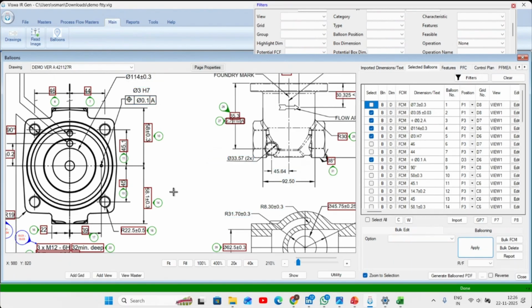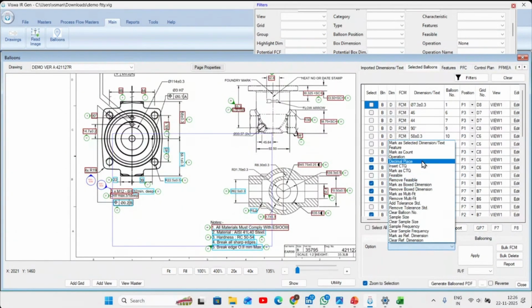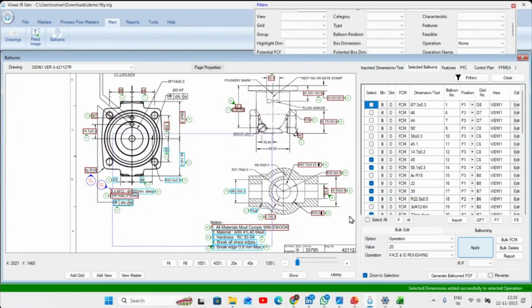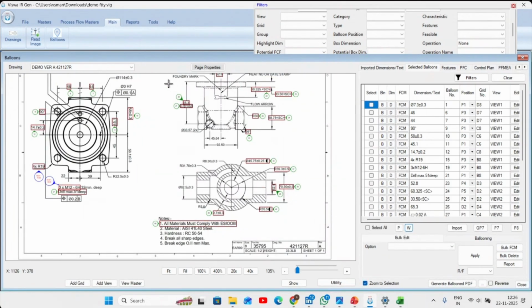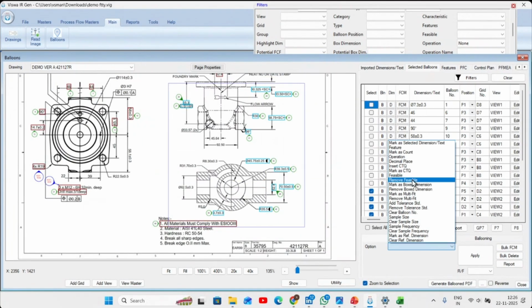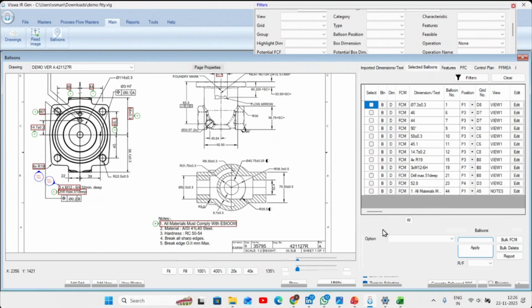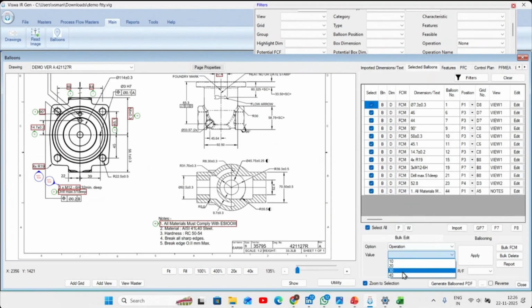So in the feasibility report you have to tell which parameter, which operation you are finishing. Correct. Yeah. So we are just distributing the parameters. The advantage here is you don't miss out a single balloon number because it's all there in the drawing, and you won't miss out a single balloon number here. Right, this is all operation 30, and whatever is left out, I'll do it in, say, operation 40.